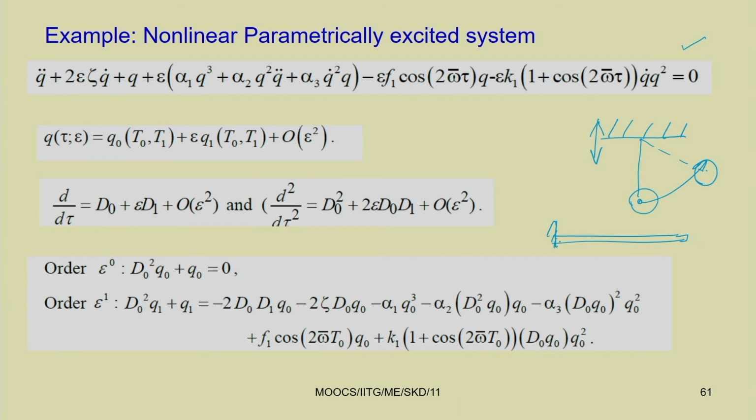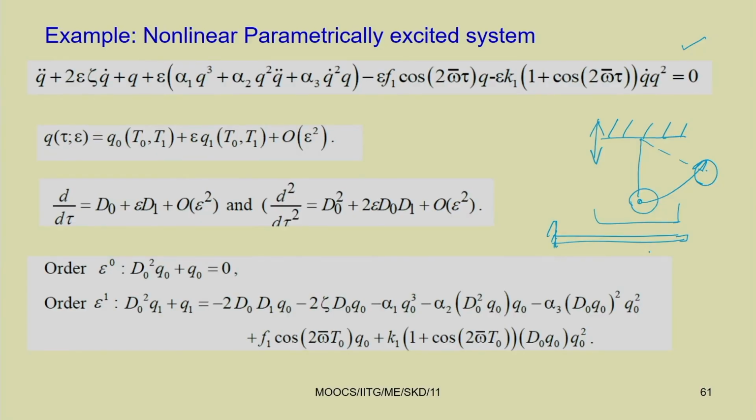magnetic field. So, this is a conducting beam subjected to a magnetic field. Due to the presence of this magnetic field, it will be subjected to a compressive load, and due to that compressive load and considering this large amplitude of vibration, the system can be considered as that of a forced and parametrically excited system. Sometimes, if that forcing is weak, it can be that of a parametrically excited system, as the system is considered to have large deflection. So, it can be considered as a nonlinear system also.